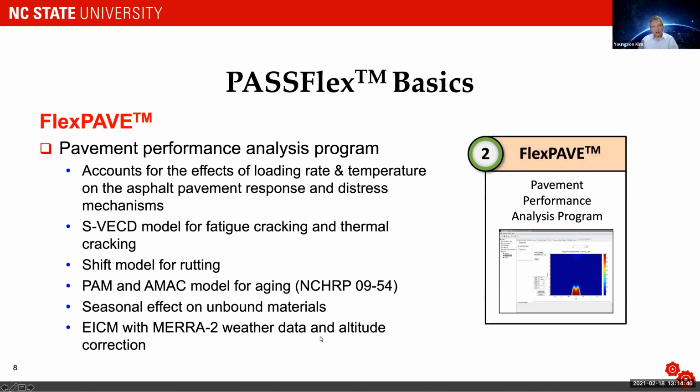And FlexPave is a 3-dimensional moving load finite element program, and it accounts for the effects of loading rate and temperature on pavement response and distresses. And we use SVCD model for fatigue cracking and thermal cracking, and permanent deformation shift model is used for rutting.